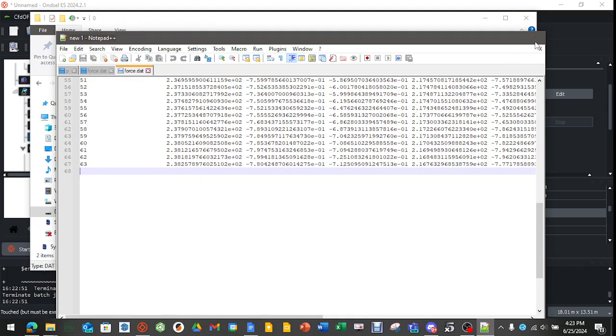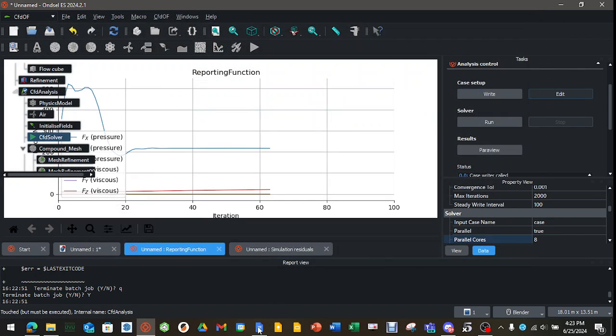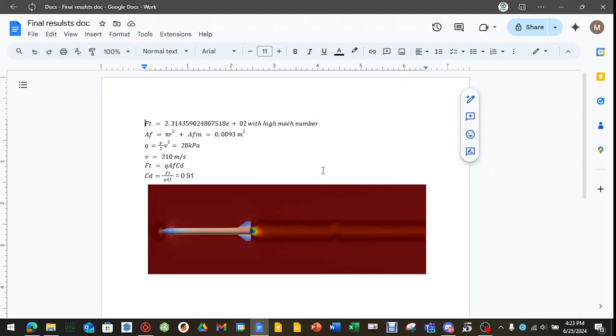So knowing that, you can either calculate it yourself or use a calculator online, it doesn't matter. Putting in the information, the frontal area, remember, not surface area. That was one of my biggest problems when I first started CFD. I was like, surface area, and I just kept forgetting frontal area because it's what the rocket's moving through. And then you can see that it's 0.91.